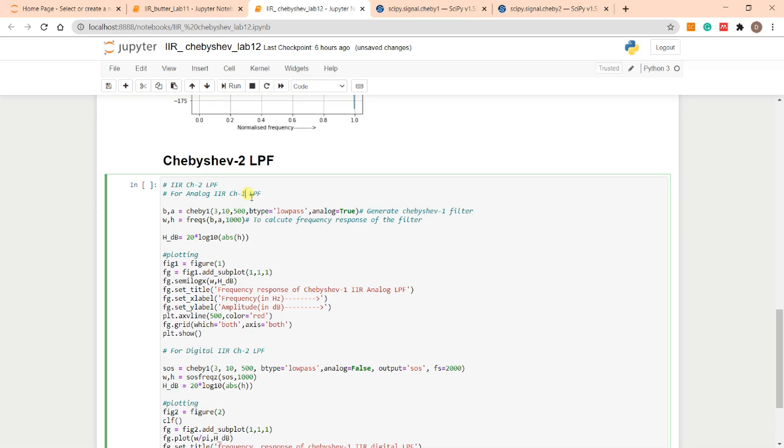The first one Chebyshev 2 filter. Okay, then we have to make the change here. That is 2. Okay, then first one is my order of the filter. Second one is the stop band attenuation. Okay, this is the maximum allowable stop band attenuation, right? So you may call it stop band ripple, maximum stop band ripple also, no problem in that.